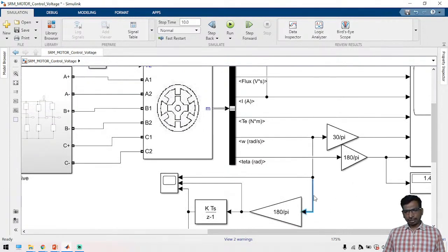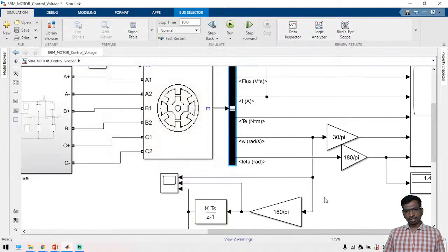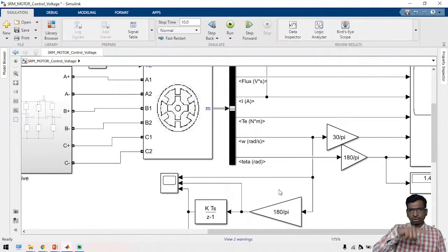So here we are taking the rotor. The last signal is omega, that is called the speed sensor. So the motor speed sensor is available on the fifth signal. This signal we have developed, and generally this will be in radians. So we have to convert to theta. From this rotor speed only we can identify the rotor position, so where is the 0, where is the 30, where is the 60 and so on, right?